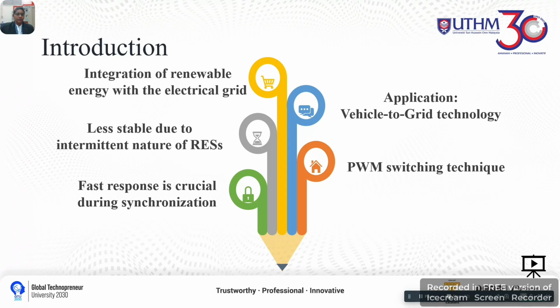techniques and algorithms. A fast response is required during synchronization to detect sudden changes in the grid, especially during an unbalanced load, to produce a smoother output with lower distortions such as in V2G technology, and also by the development of fast DSP such as FPGAs and solid state switching device technologies.